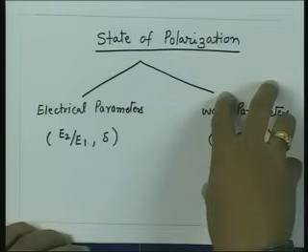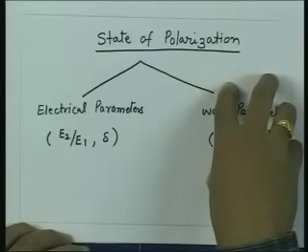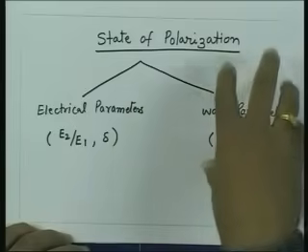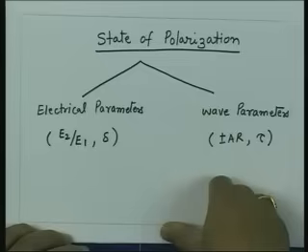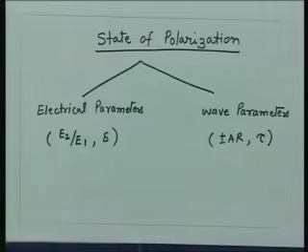So, for generating a particular shape of ellipse or a particular wave of the elliptical polarization, one would ask what parameters should be set electrically while generating this wave. So, we would need a relationship between this and this. Conversely, one can ask a more analysis-like question: if I had two linear polarizations, vertical and horizontal, and if I excite them in certain proportion with certain phase difference, what kind of ellipse will be generated.